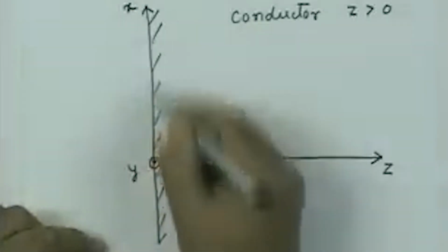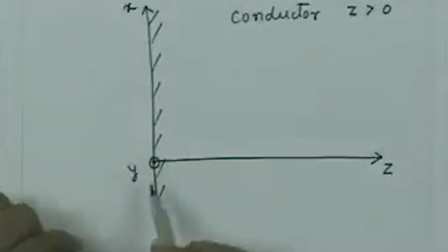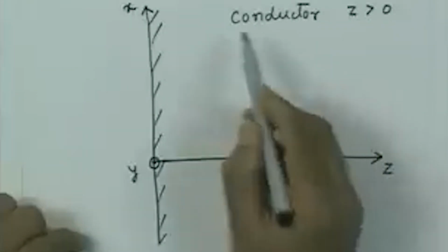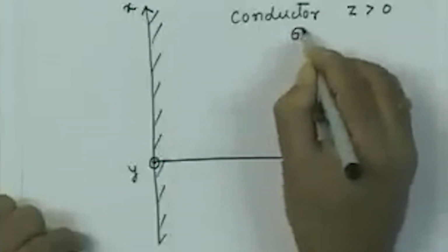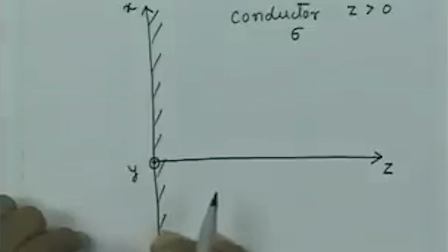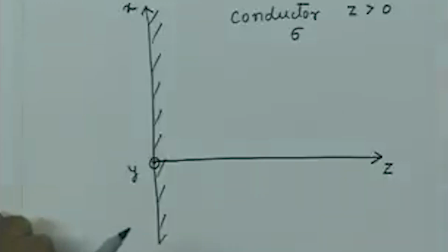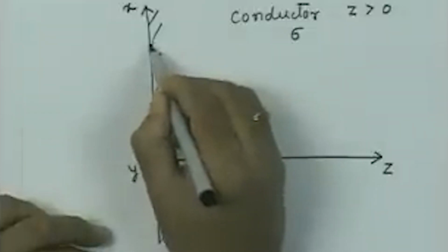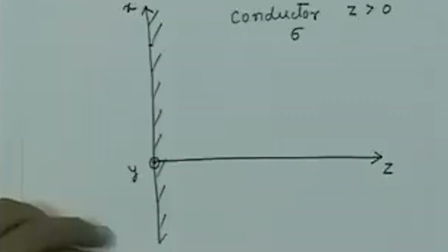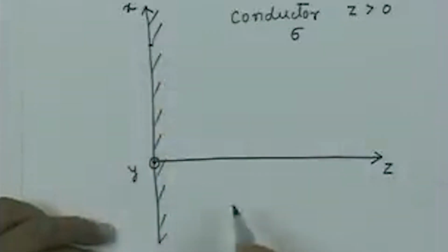Now if I have some electric field at the surface of the conductor, note here, since the conductivity is not infinite, this is not an ideal conductor, I have a conductivity for this conductor which is given by sigma. So the tangential component of electric field is not 0 now, because the conductivity is not infinite. So let us say I have a certain value of electric field in this direction, and that electric field essentially will exponentially die down.